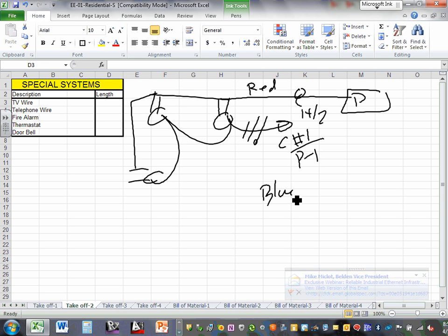Well, unless you can reach it through the wall. Can you reach the panel through the wall? It depends where you are. If one is closer to the panel, look at this. If I want to bring this receptacle to the panel, I have two options: going all the way up, or come across, down, over. I will go this way. So choose the closest if you're in the same wall. I would come from here, maybe around 4 feet, just 4 feet as you go up. So for termination, come from the receptacle, crossing up 4 feet to go into the panel from the bottom.